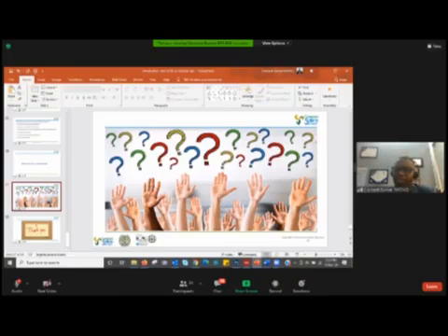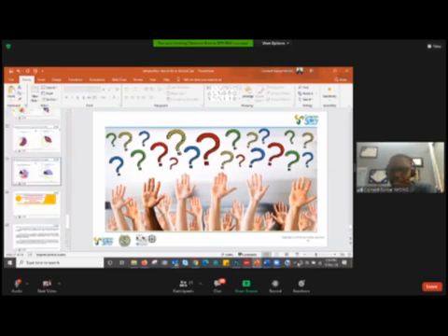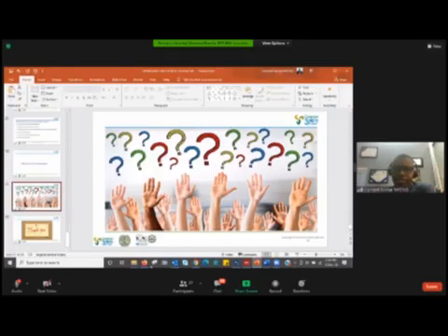You know, hydrogen sulfide is heavier, denser, so it settles in lower places. So what will be done is to put people at the uppermost part of the rig, usually at the heli deck for offshore. People will move to the heli deck, and they will also be advised not to follow the direction of the wind. You need to move opposite the direction of the wind. So these are some of the things that are being done to reduce people's exposure to the risks that can occur as a result of exposure to hydrogen sulfide.